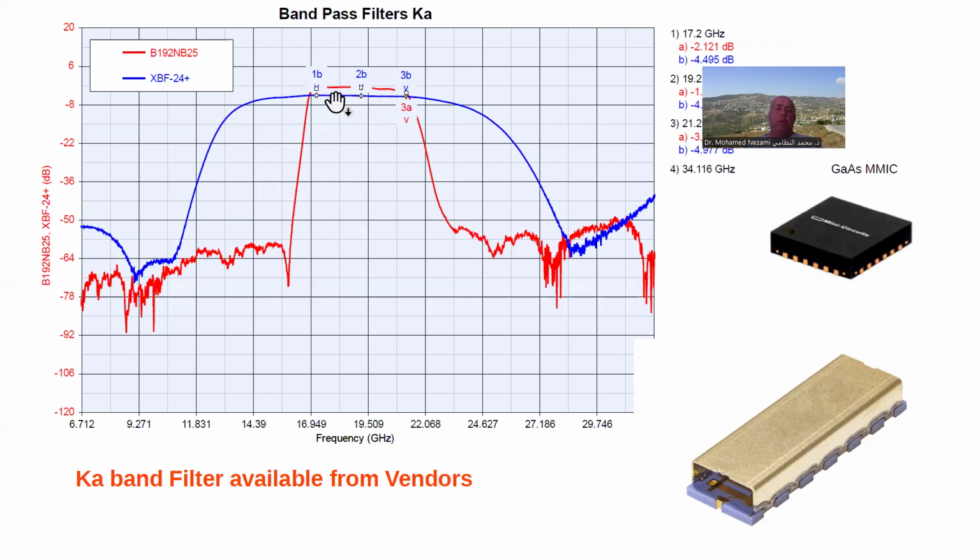That's a nice filter that they sell right now, but it's very expensive. It's like $100 to $150 a piece. Plus, by the time you really get it to work on the board, all the parasitics, the grounding issues, the isolation issues, it becomes a headache.